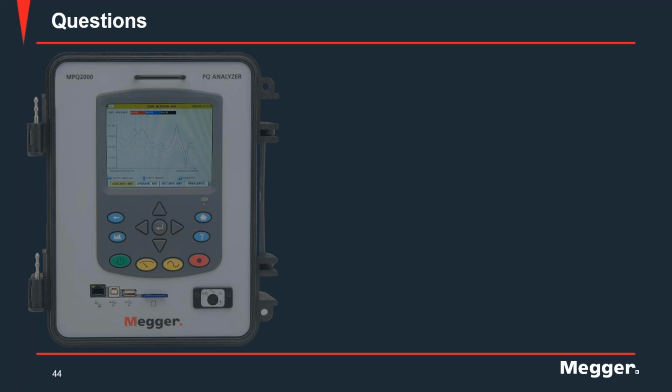Now, on the con side, since they do operate off DC, that means they have to have an AC to DC rectifier in them. So they do create harmonics. Now, we're talking very low current here, so it's very minimal harmonics, but if you're replacing an entire facility with them, it is recommended to do a harmonic analysis before and after, to see what impact it may have on other systems.